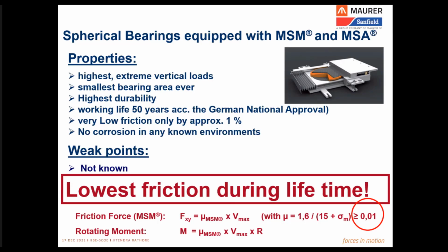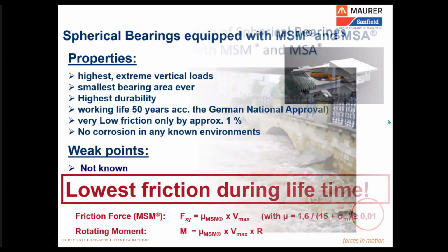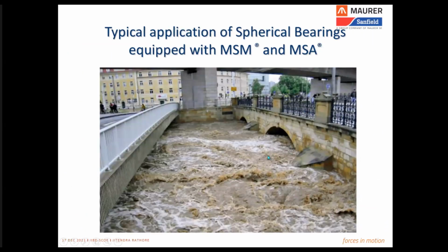But in many countries, to avoid the issues of corrosion altogether, they are going for complete stainless steel bearings. In our country also, there have been very few, maybe you can count on your fingers, very few projects where for some special requirements, they have gone for complete stainless steel bearings. So these are the possible innovations or advancements, you can say, to overcome the corrosion concern.